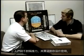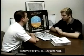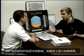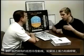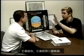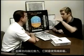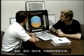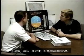People say asymmetric thrust, which really doesn't do much for you, but the thrust really does play a major factor in pitch. With the low slung engines that we have, if you add thrust and the lever arm that it gives you, it'll give you a pitch up. If you pull thrust back, it'll give you a pitch down. Finally, there's another law called abnormal attitude law.